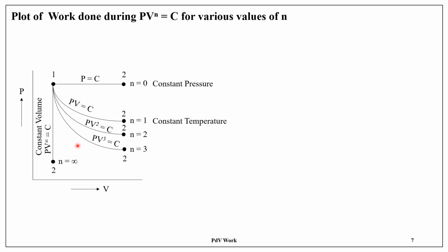So again, it is something like a polytropic process where gamma equal to 1.4. But we don't call that a polytropic process, we call it a reversible adiabatic process. And what is the value of n in general for a polytropic process? It ranges between 1.1 to 1.3.